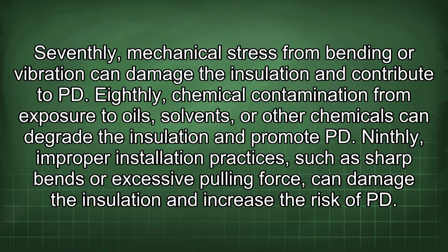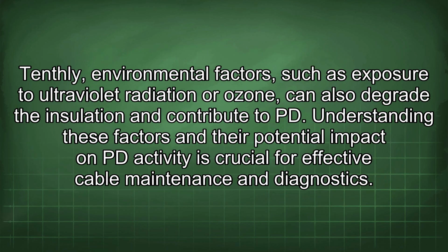Ninthly, improper installation practices, such as sharp bends or excessive pulling force, can damage the insulation and increase the risk of PD. Tenthly, environmental factors, such as exposure to ultraviolet radiation or ozone, can also degrade the insulation and contribute to PD. Understanding these factors and their potential impact on PD activity is crucial for effective cable maintenance and diagnostics.